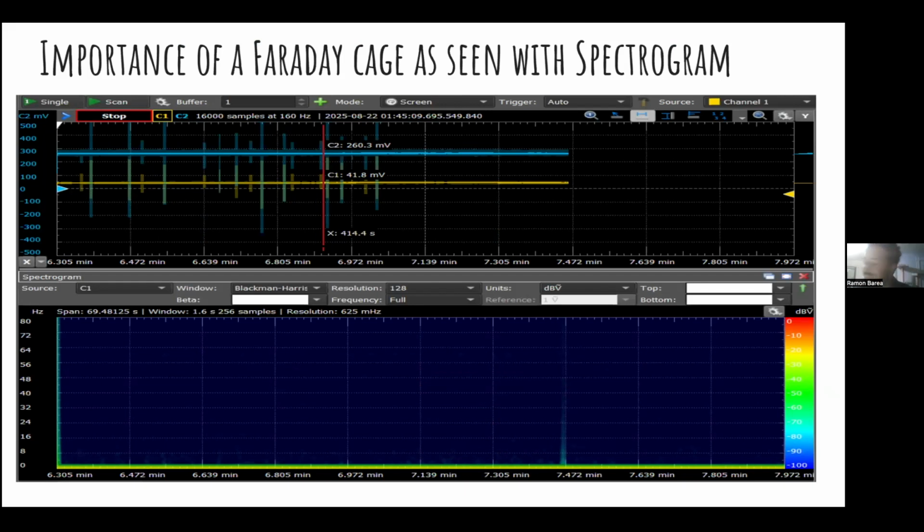But I feared that there's electromagnetic interference from the light itself, as opposed to it being the UV light response. So I disconnected the electrodes from the mycelium and repeated the test, and I saw these little blips again. And I saw, okay, yes, that's electromagnetic interference from the switching components of this UV light. Good to know, mistakes happen and we keep on going. But that's the reason why Anand had used the Faraday cage, because we're trying to measure such small voltage that any little bits of interference and noise can ruin our results.